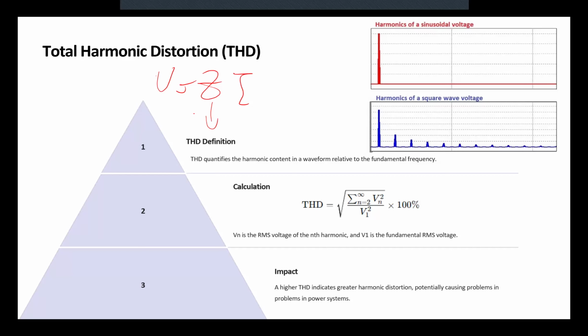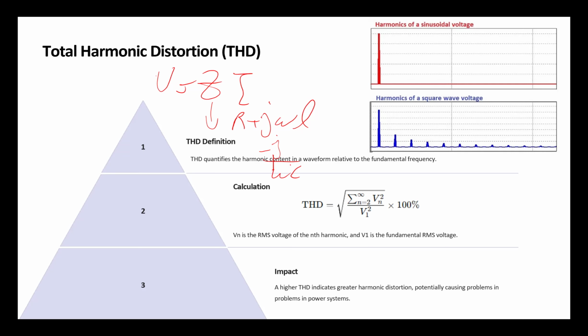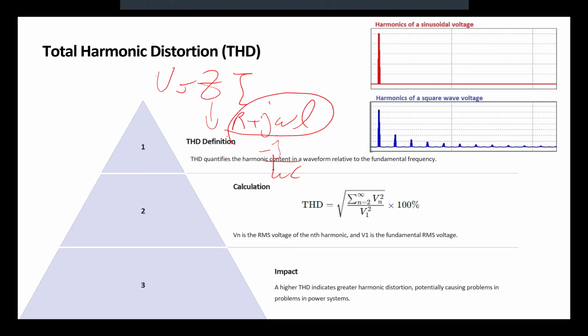Correct? Because the real part was resistance, we say it doesn't change with frequency. But the imaginary part is the inductance, either j omega L or minus j over omega C. A power system normally is an RL system, where L is much higher than C, so you mostly see such an impedance.